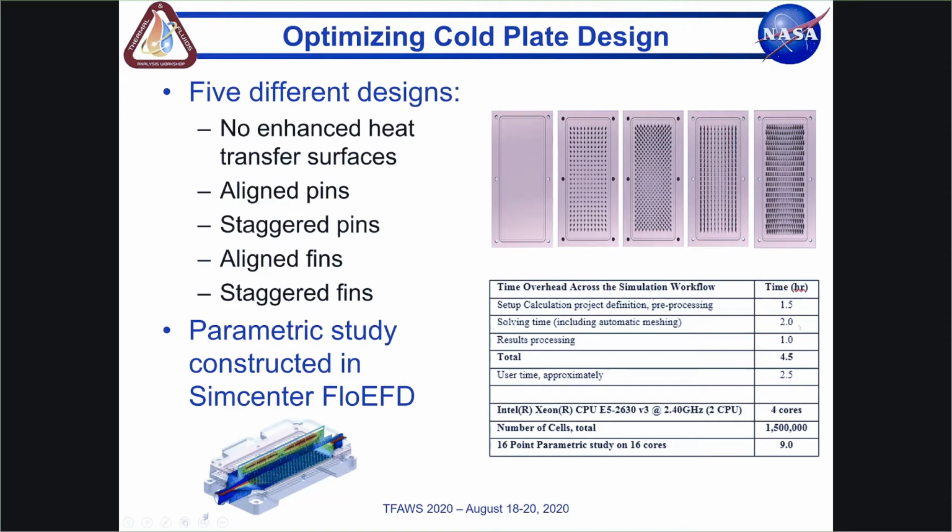So setting up the model from pre-existing CAD, defining materials, setting boundary conditions, setting up the mesh, that took about an hour and a half. The solver time for the initial case took 2 hours to solve, including the meshing time. And then post-processing the results, maybe making these nice, pretty pictures, took about an hour. So total time to run a single case here was about 4.5 hours, which, we've seen in the field, is up to 10 times that amount of time with traditional CFD.